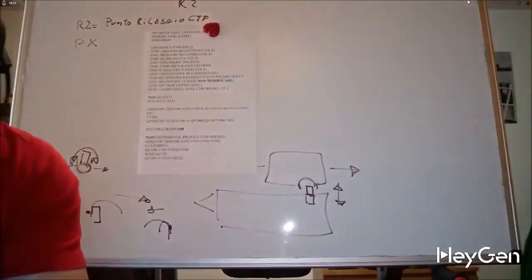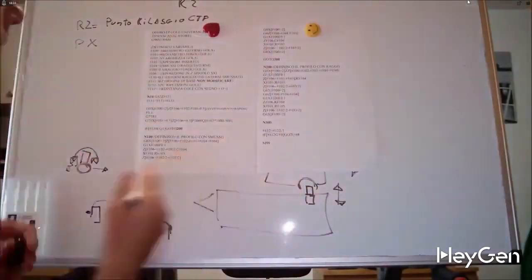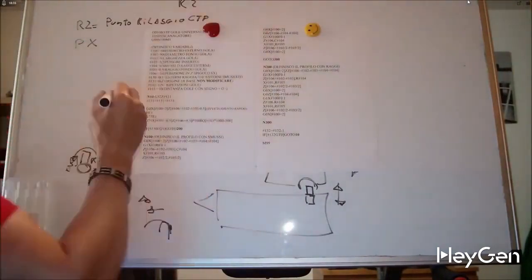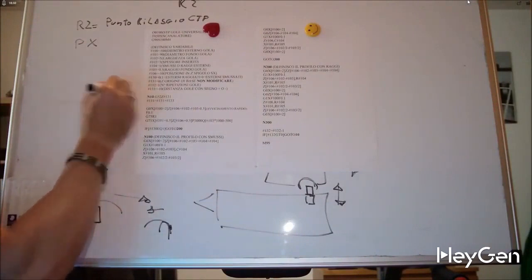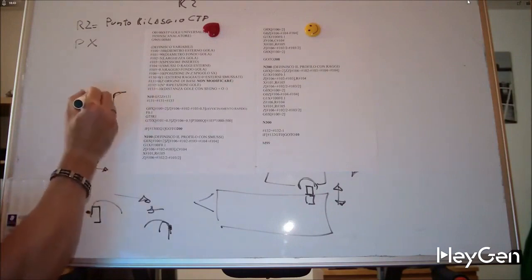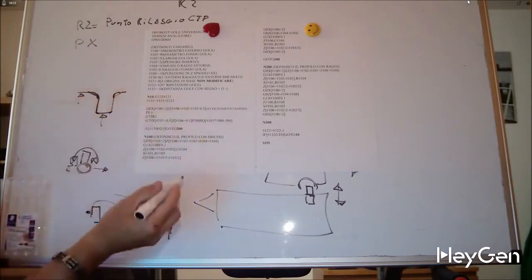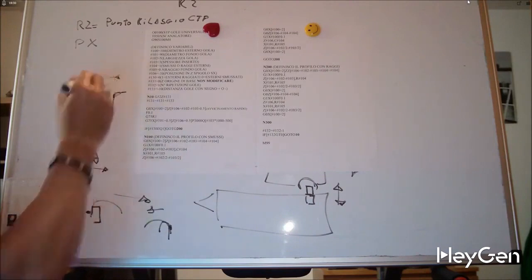Origin. This is a subprogram to decide whether to create a groove along an outer diameter that has chamfers or radii, with a bottom groove radius of a certain size, a starting diameter, and a bottom diameter determined by the variables, a width determined by the variables.